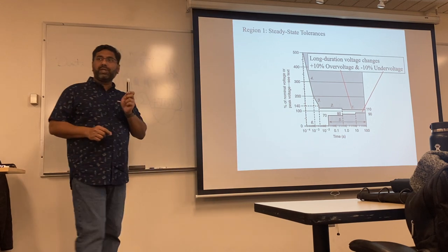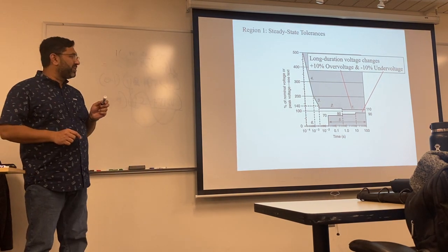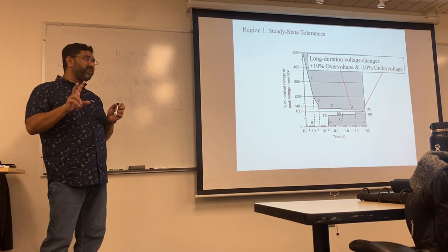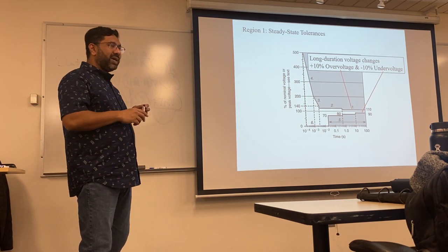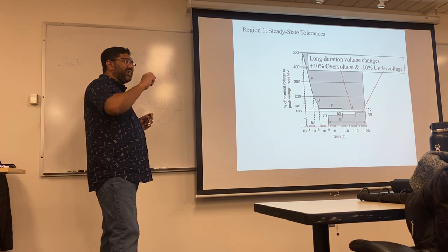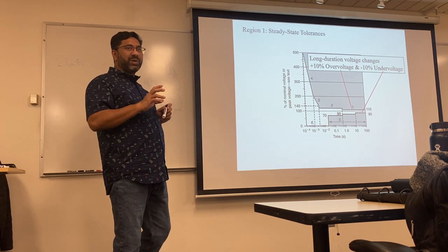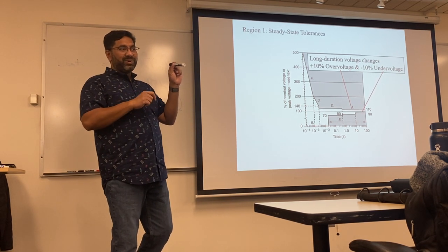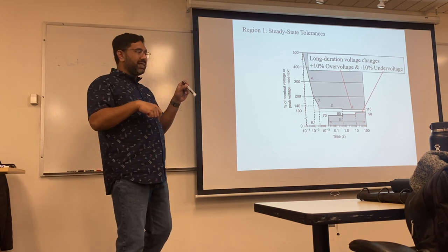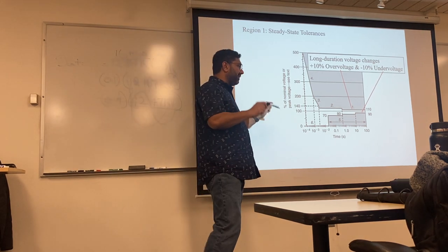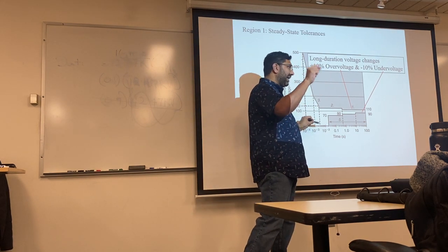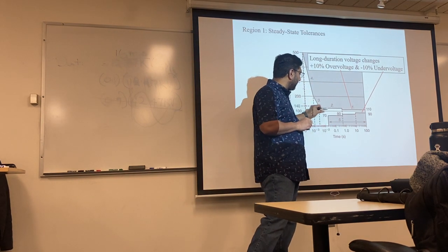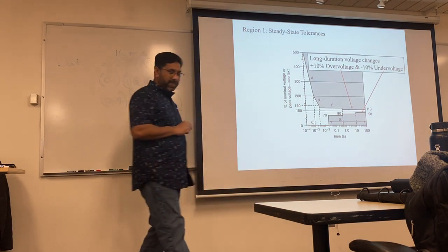So if you guys were doing the project, there's a trick to doing the project where you have to actually choose a fuse. And in the lab, the fuses are just lying there. If you don't read the proper fuse, every day you're just blowing up fuses and not realizing what's happening. You're checking your wiring, you're going to the next guy and asking, and they're coming and checking the wiring, not realizing you picked up the right ampere, but you didn't pick up the right one. There's a letter after the fuse which tells you how long it can sustain the time. Just look it up.